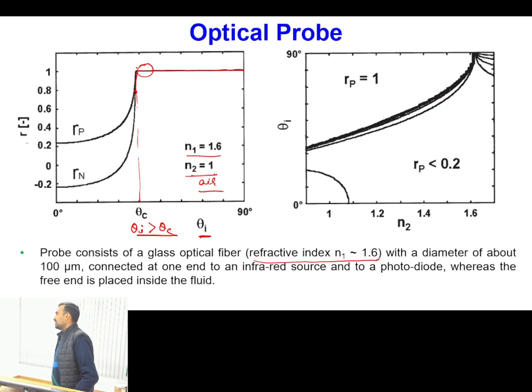This type of information is very useful, because if you have any distortion in the placement of the detector, that will also be accounted for, as the strengths of both signals are the same, and at the same time you will get a strong signal at the output in comparison to the weak signal observed for an angle of incidence less than the critical limit.